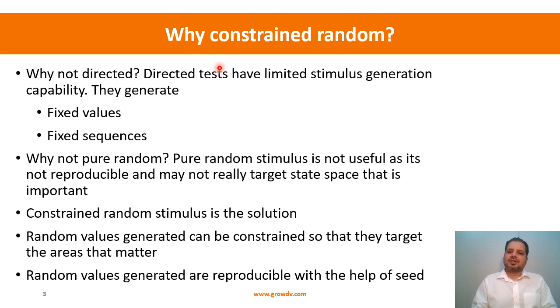So it could be a series of transactions that you are generating, and in the transaction you have the variable. For example, in the FIFO, we generated a series of push and pops, and the data that we are randomizing is a variable. The delay between operations is a variable. Those are the two things that we were randomizing.